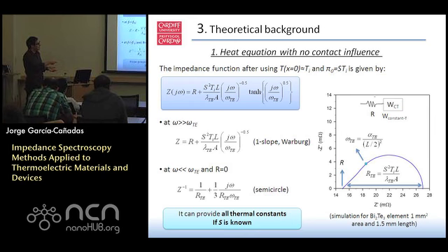And then the diameter of this kind of semicircle Warburg is given by this equation. This has unit of ohms, and we call this thermoelectric resistance. If you look at it, it is the ZT figure of merit without the electrical conductivity contribution, and taking into account also the geometry of your leg.